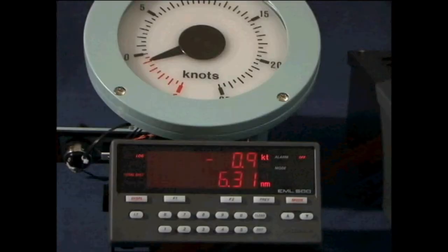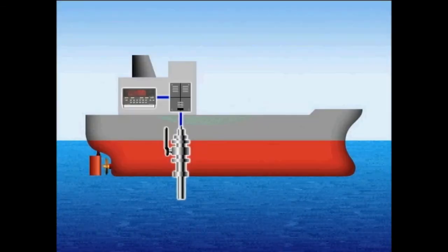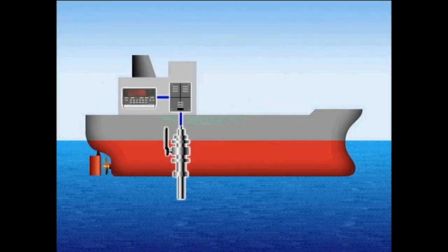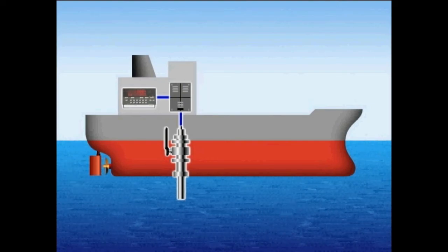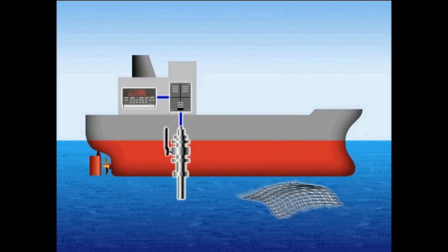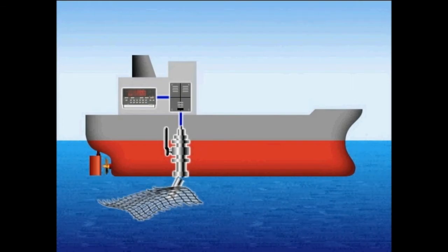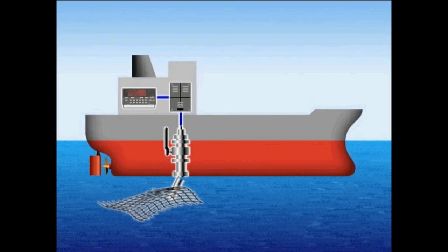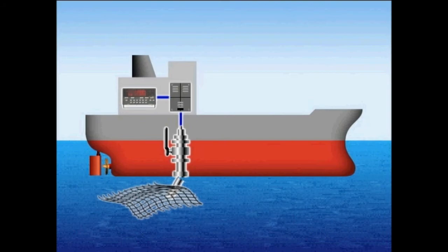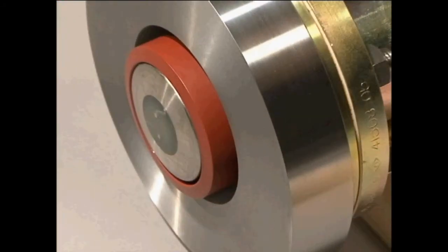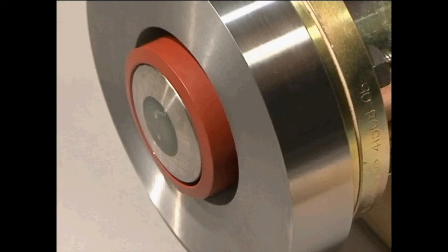The EM log also gives accurate speed indications at slow ahead and astern. The sensor protruding into the sea reduces the influence by the ship's wake and enables highly accurate measurement. However, the sensor is at risk of colliding with obstacles such as driftwood. Therefore, the newest EM logs are flat and the sensor does not protrude from the hull bottom.